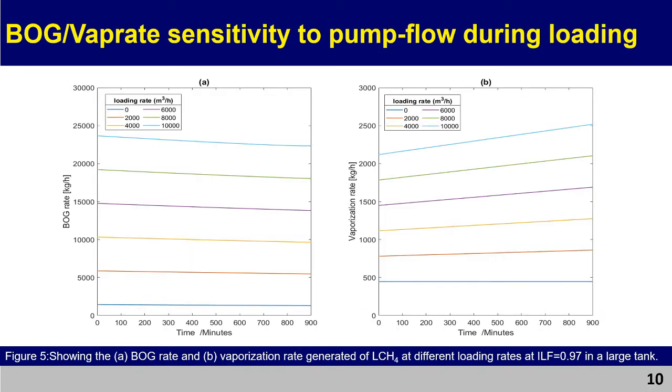During loading, you can see that as you increase the flow rates, the BOG increases, and the vaporization rate also increases. This is a result of the volume of LNG in the tank increasing, so the heat ingress into the LNG is also increasing.